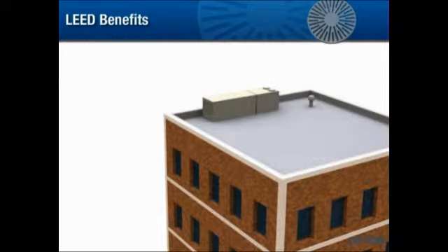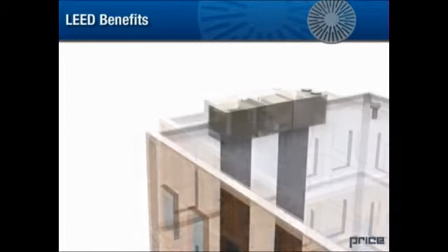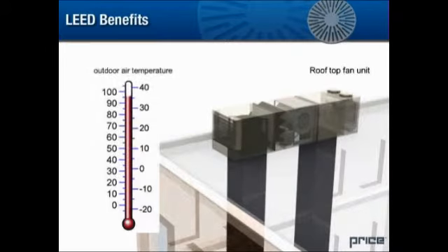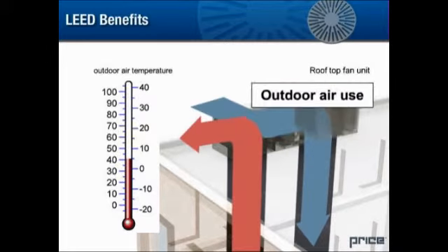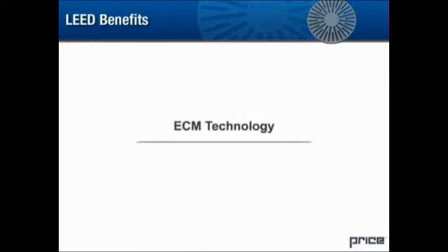More free cooling. The higher supply air temperatures associated with underfloor air distribution allow for an extended free cooling band. This means that more hours during the day are available for the ventilation system to use outdoor air to cool the building. This leads to increased use of the economizer, an excellent way to reduce energy consumption.